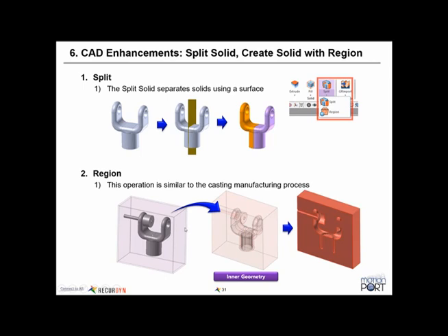So basically, with the ParticleWorks and the EDEM models, sometimes we're generating this place for the particles to go. In this case, you can have a solid model and put that within a big block. You do the region operation, and it will create a cavity in the block where it subtracts out everything for that particular body.